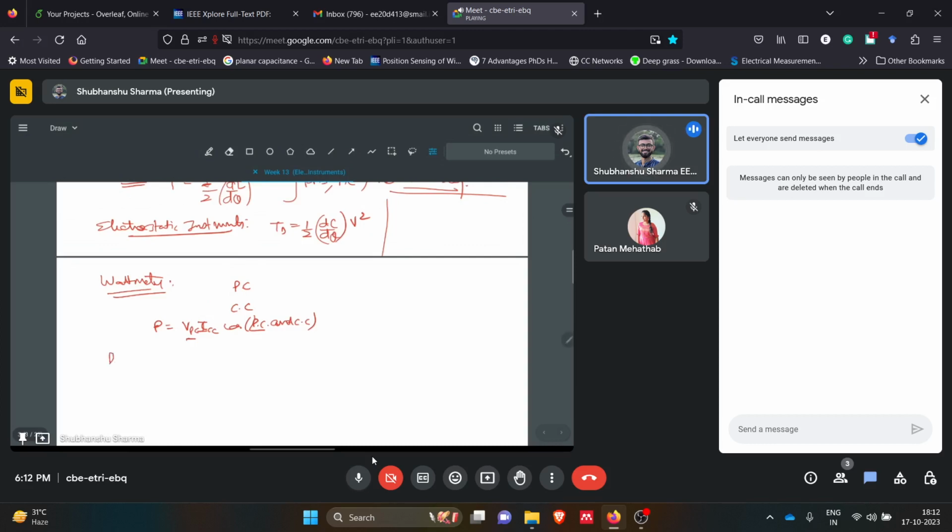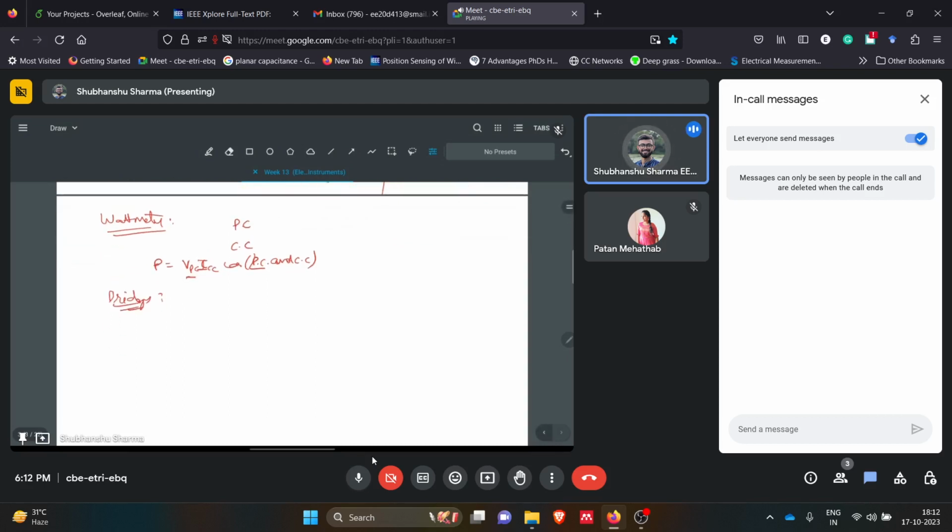There were lots of different types of bridges. We saw Wheatstone bridges, and we applied the basic concept of Wheatstone bridges to many AC bridges, to measure different types of capacitances: low value, medium value, and even high value capacitances. Same for inductors, we saw different bridges, like the Maxwell inductance bridge, if this has been taught to you. We also talked about how to reduce the lead resistance in a particular measurement using bridges. That was the Kelvin double bridge.